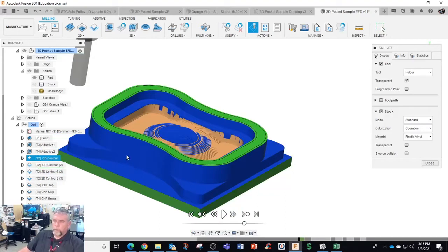So let's go to finish the outside contours with flat end mills, do the chamfering, do the whole work, and we'll probably finish with a strategy to do the 3D machining on the inside.